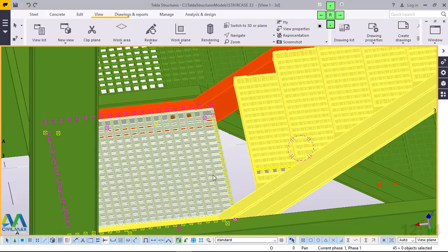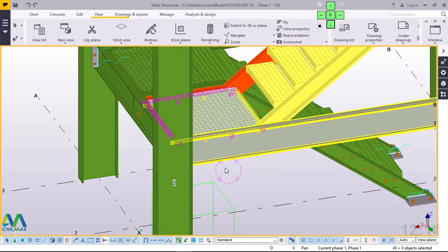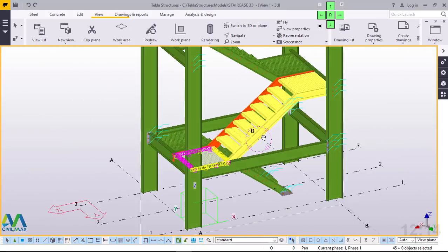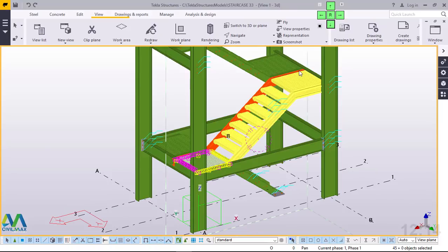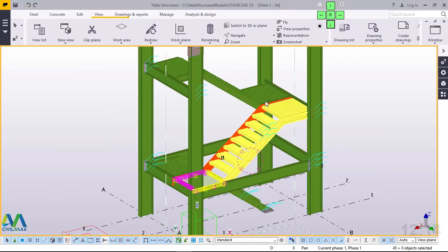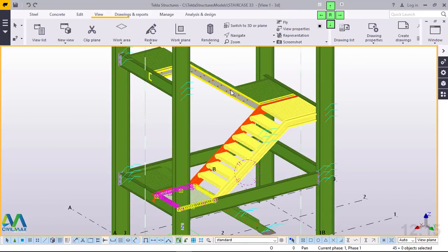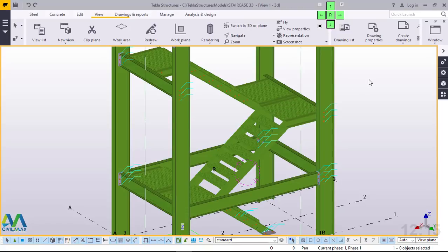Now the next step, I want to populate all these to the height of 60 meters or 57 meters. Now it is simple. I'll press Alt. Now I'll deselect everything I've done and click on this. And click on that.